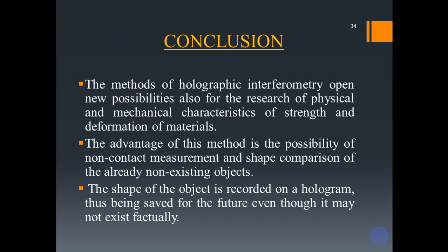In conclusion, the methods of holographic interferometry open new possibilities also for the research of physical and mechanical characteristics of strength and deformation of materials. The advantage of this method is the possibility of non-contact measurement and shape comparison of already non-existing objects. The shape of the object is recorded on a hologram, thus being safe for the future even though it may not exist factually.